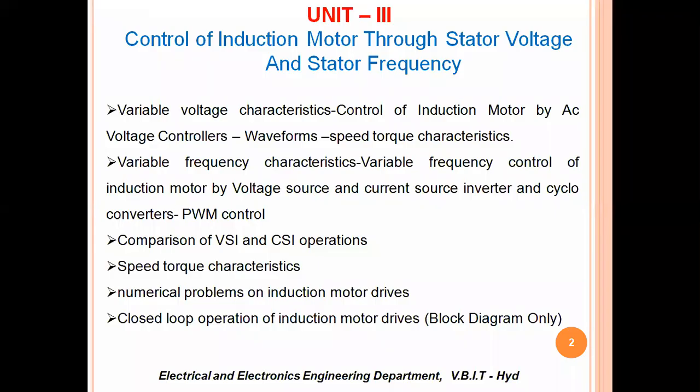The main drawback of DC motors is the presence of the commutator, because we use a commutator on the DC motors in order to convert that AC generated EMF into a DC value. Because of that commutator and the brushes to collect the current generated by the motor, these are the major disadvantages. The commutator and brushes increase the weight and the size of the motor, which means the cost of the DC motor will also be more.